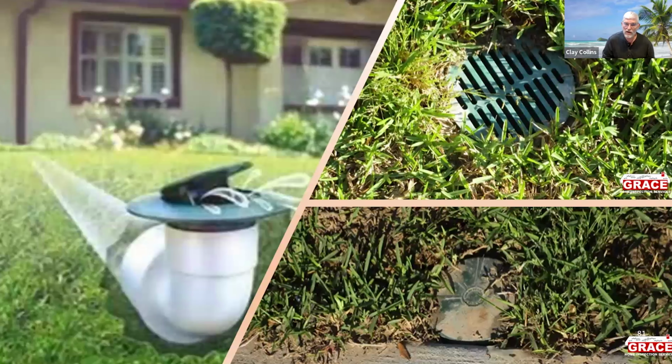You have the illustration, and you see that the downspout is purportedly going directly into that. But to do it that way, you would have to have one pop-up drain per downspout. So usually it comes together in a grid and all goes to the front. But you can also see what I was talking about, how the volume will overwhelm that 4-inch pipe there. It just can't handle the volume of every downspout.